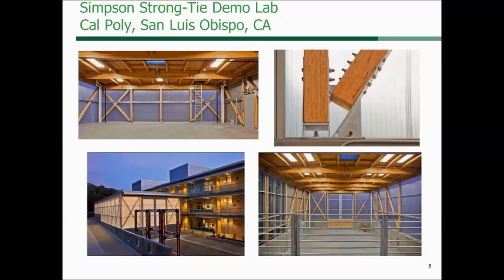This used heavy timber braced frames for the lateral system, which, for those of you that are familiar with the Uniform Building Code, was a prescriptive method of providing lateral resisting systems. For some reason, when it transferred to the IBC, it was no longer a prescriptive method.